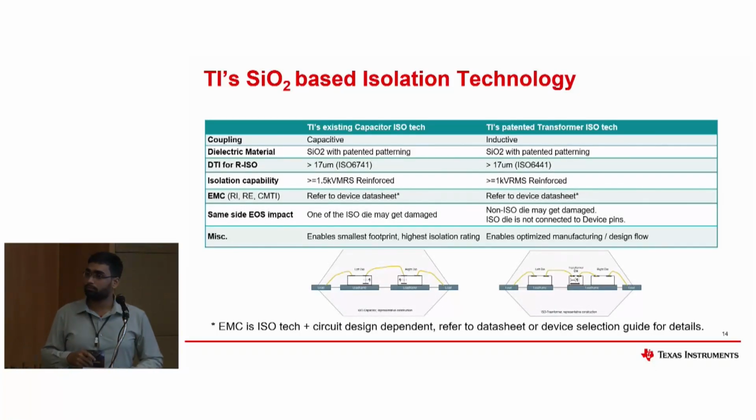So this is a new technology that TI developed for the ISO device, right? I think what I hear, that's the previous one, you have two silicon, and then you add another silicon. This is, I think, 3. Yeah, the middle silicon is like a transformer. Yes, this is the isolation die, which gives high voltage protection, whereas these two are the communication dies.